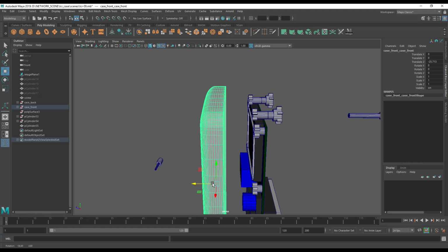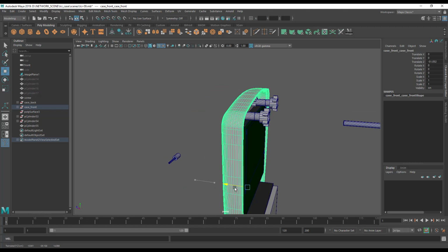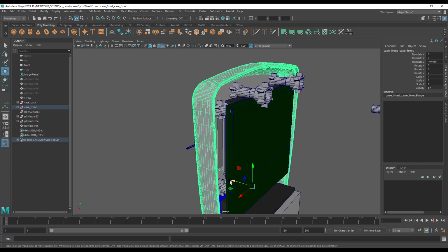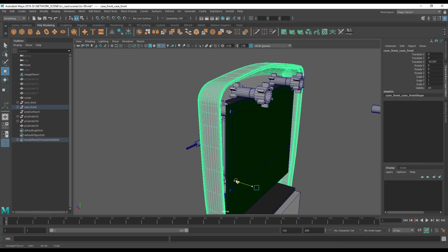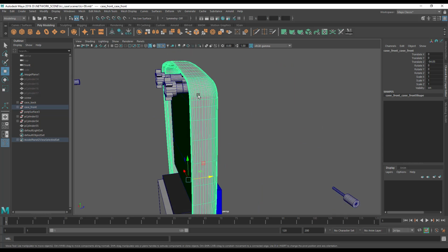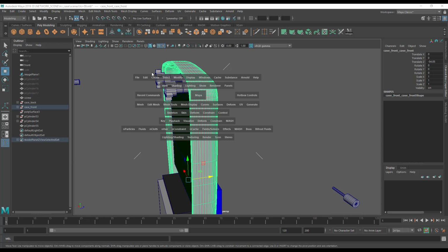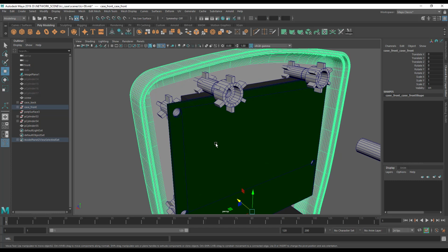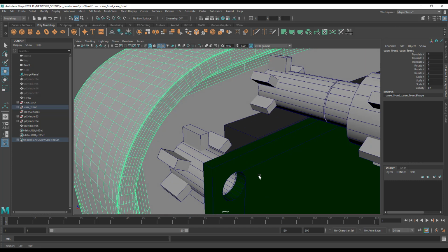Let me see. No, it is just as simple as I've moved it out of position and frozen its transformations during probably a demonstration or some such. So just move that in until it bisects the front again. There we go, and reset its freeze transformations. So modify, freeze transforms. There we go. Sorry about that little mistake there.